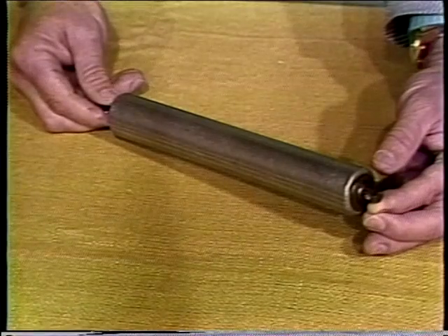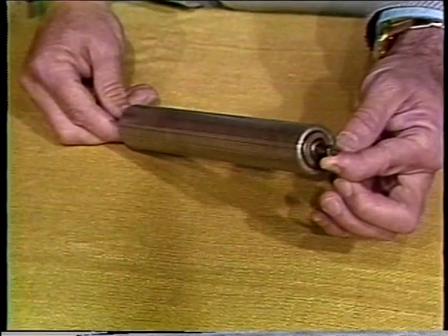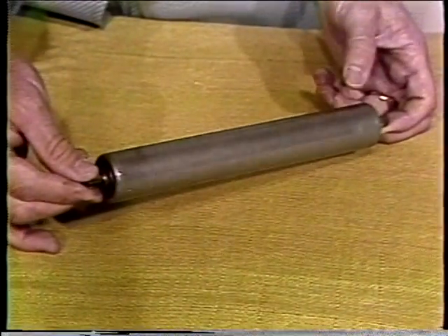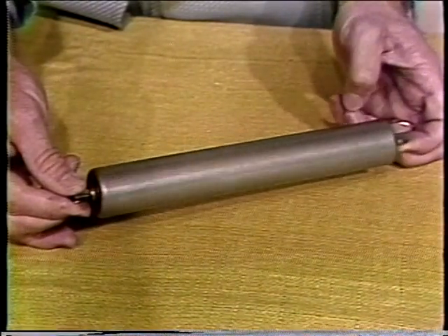bottom of the rollers. The rollers themselves may be spaced very close together or wider apart depending on the weight of the material to be handled and the size of the bottom of the box. If the product to be handled is small, it may be necessary to put it on a pallet. On a roller conveyor, the rollers themselves are nothing more than steel cylinders which have a bearing mounted in each end. These bearings are usually non-precision type, since individually they carry very little load.